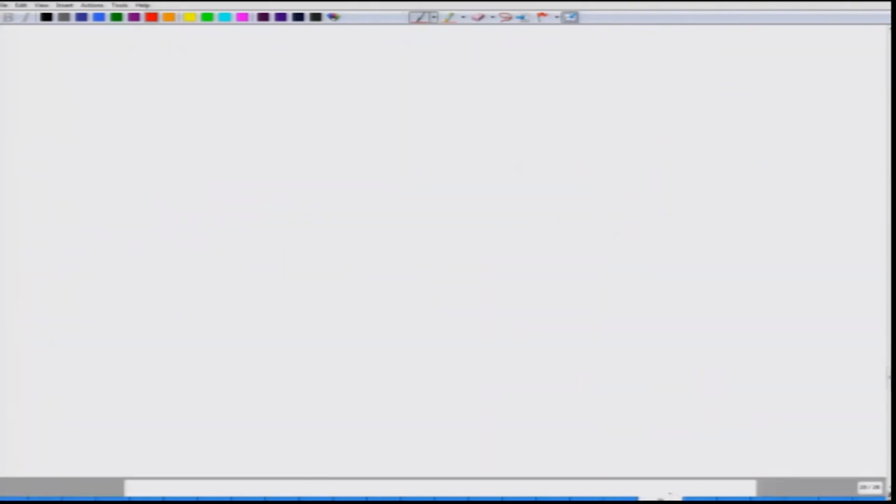Okay. Now, instead of working with free space, which we used just to understand what was happening, we now want to consider what happens through the fiber. Since I am considering the fiber, I know that beta will be some function of omega, correct. But now I am going to assume that my pulse, instead of being just a pulse here, I have actually modulated this pulse onto the carrier, and let me take the carrier frequency as omega 0. Okay. This is how you normally transmit optical pulses. So, we actually go to this kind of a consideration.